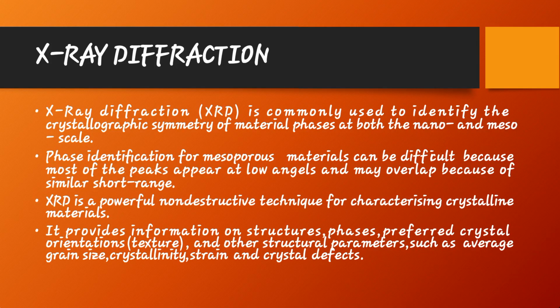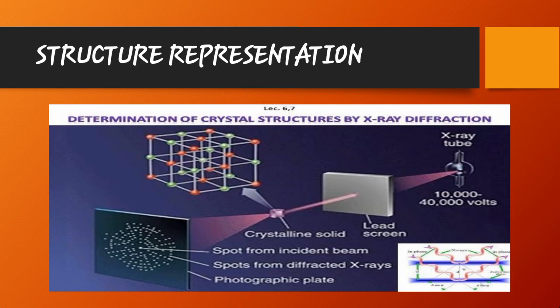X-ray diffraction is a powerful non-destructive technique for characterizing crystalline materials. It provides information on structures, phases, preferred crystal orientations, texture, and other structural parameters such as average grain size, crystallinity, strain, and crystal defects. Here is showing the structure of X-ray diffraction.